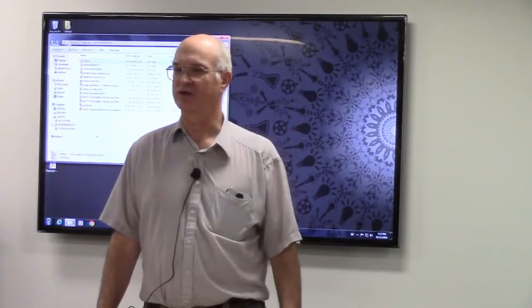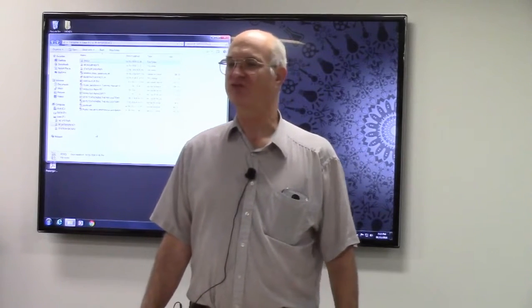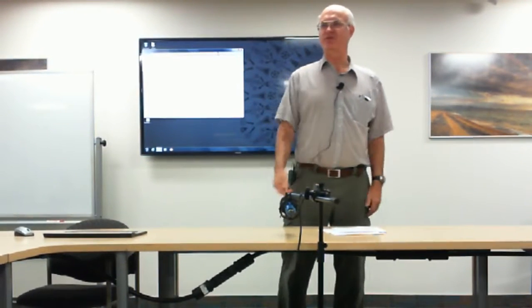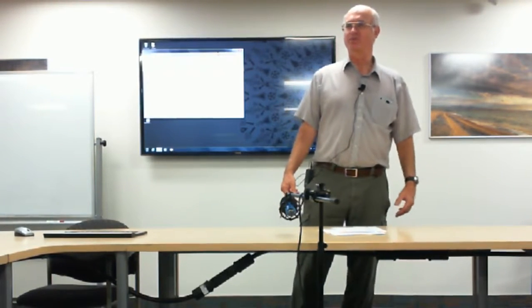Audio rectification is probably one of the most common problems that you're going to experience with radio frequency interference. It essentially works like this. When you transmit a radio signal from your radio, it travels through the air. That radio signal is then picked up by an object, say an antenna, and it's fed into your receiver. This is usually a piece of wire or a conductor. Well, your neighbor has a stereo system, and he has wires connected to it that go to his speakers. So these speaker wires will act like antennas. Radio frequency doesn't know any difference. It sees it as a dipole.